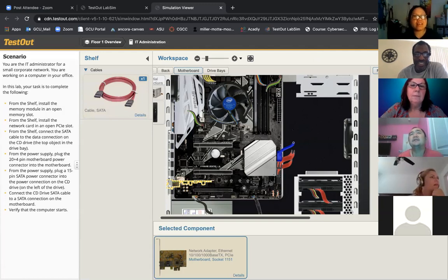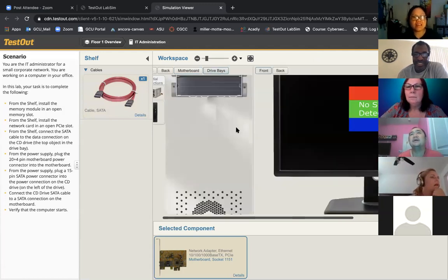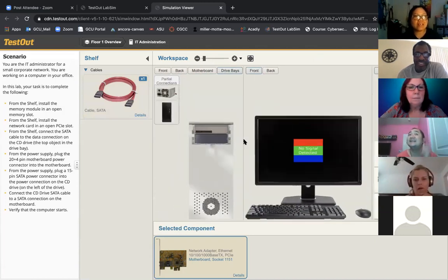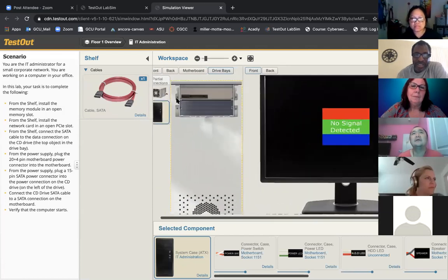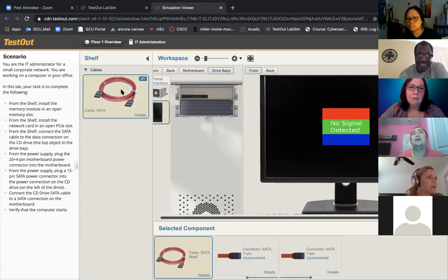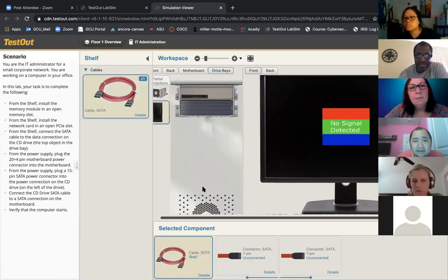The box on the top is that one. And we have to actually, this is too easy. They give us, and essentially it shows you where you're placing that. So right in the back, internally, you'll see where your drive would slide in, essentially either a CD or a hard drive. All right, so now what? What do we do with this cable? Connect one end to the number 2 for the power supply and the SATA cable.